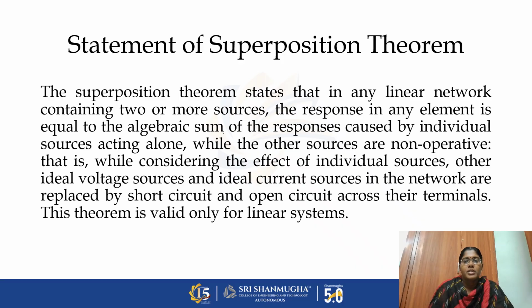This superposition theorem states that in any linear network containing two or more sources, the response in any element is equal to the algebraic sum of the responses caused by the individual sources acting alone, while the other sources are non-operative.